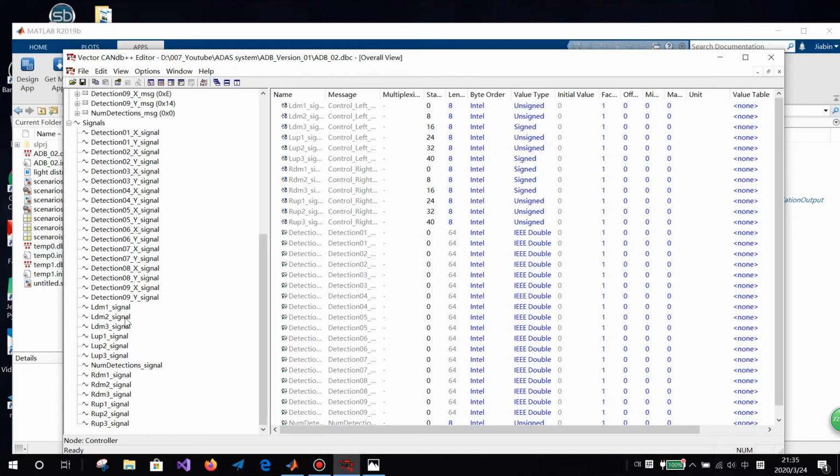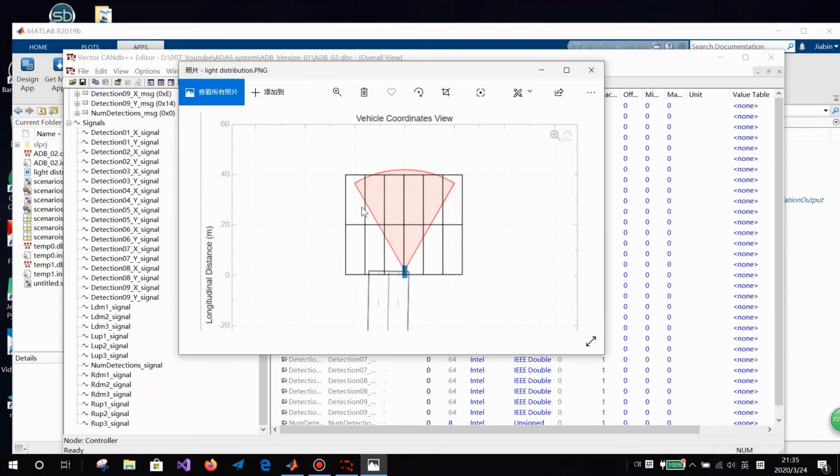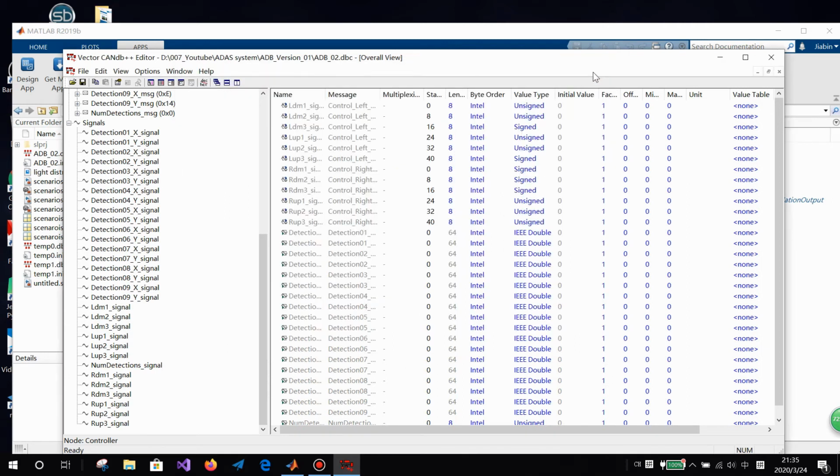In total 12 signals. When objects show up in one of the lighting areas, the LED will be turned off. And for the driver, we will just use a set of PWM generators instead. Later we will have a look at the whole system.